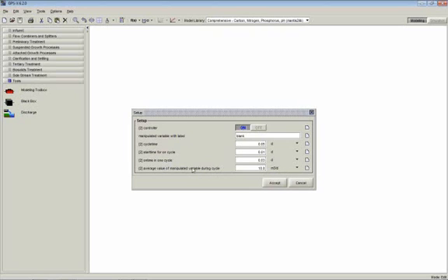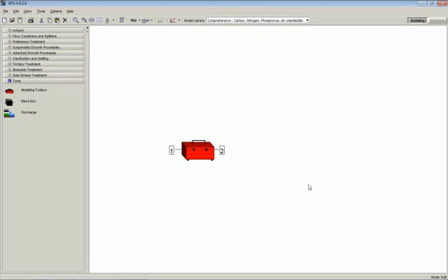The reason this is very handy is if you're saying to yourself, I would like to waste a certain amount of sludge from this tank over a certain period of time, and I know that I'm going to do it over a couple of hours each day, and I know I want that overall mass to be a certain amount. This will do that in a very straightforward way by allowing you just to specify what you want the average flow out to be, and we'll calculate what the rate of flow should be for the given on time that you have provided.